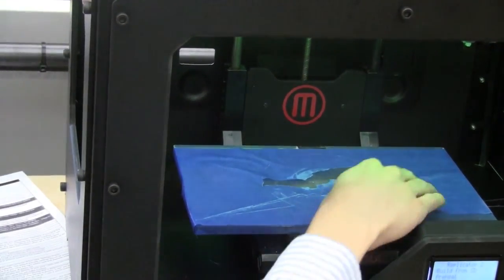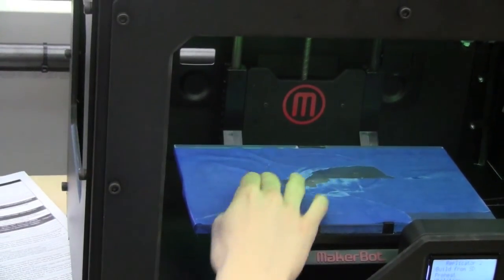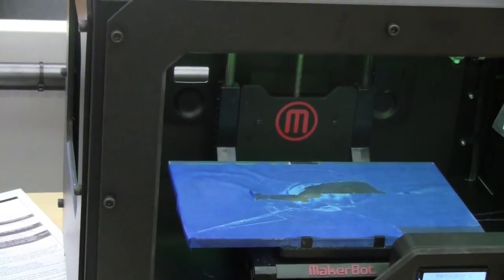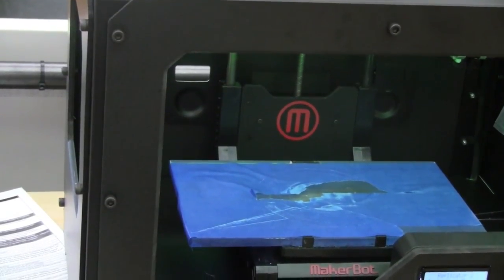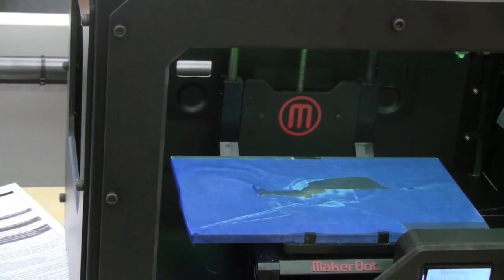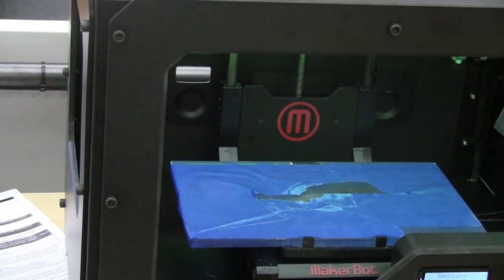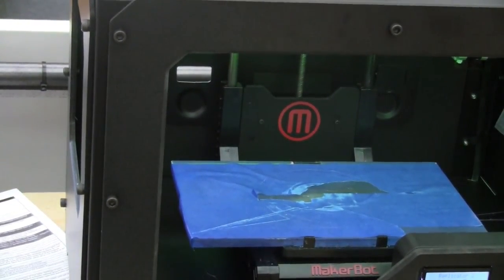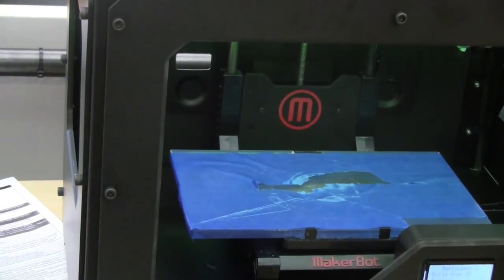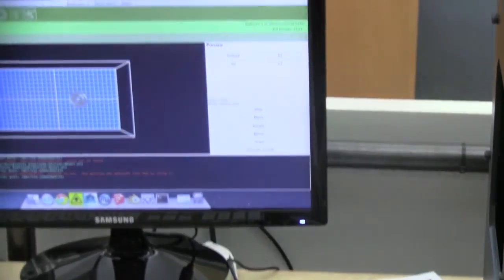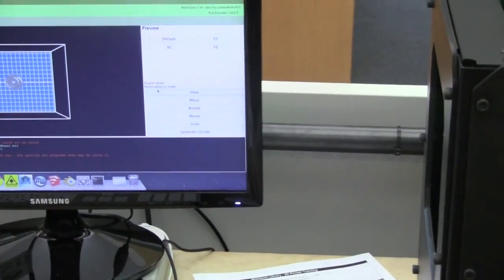If you were to print on scuffs like this, it'll leave a visible imprint on your model, and it might be harder for the print to stick, especially on the Replicator 1. So then you move it. Now, if you weren't in the default view and you thought it was actually on the left, it would be on the right, and then you might put it onto a scuff and you might waste more time, that kind of thing. So that's when default view comes in handy. You can also just use the top view for finding out position and stuff. So that's how I use view mode.